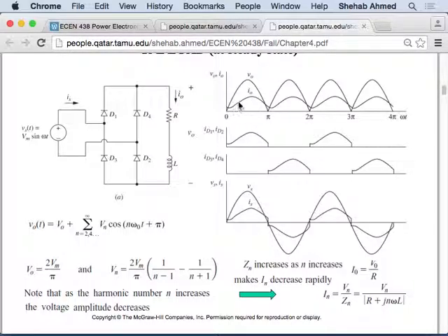At some point, it will rise, for example, and then the inductor, if it's infinitely large, the current will just be flat. It will not change, right? So forget about the initial transient. Initially the inductor had zero current, forget about that. In steady state, the fictitious case of an infinite inductance would mean that this value of current will be just flat, right?